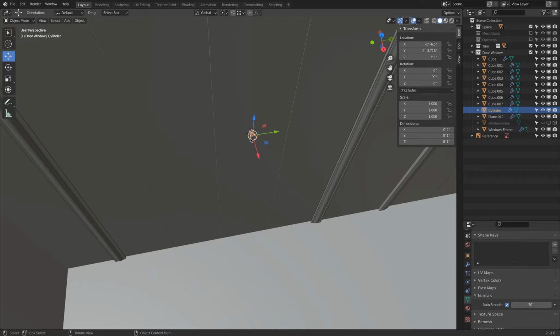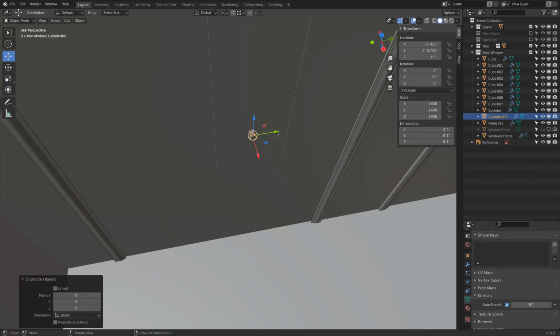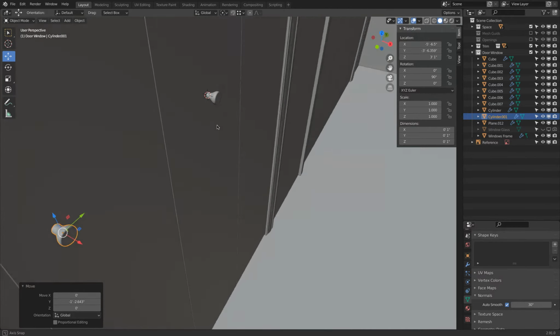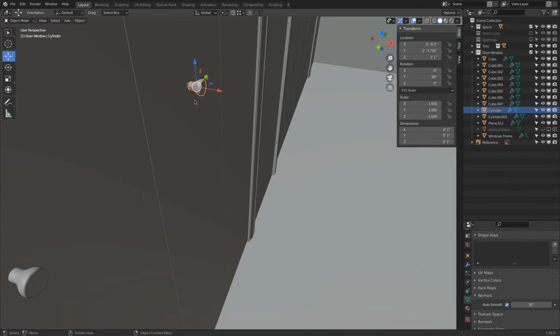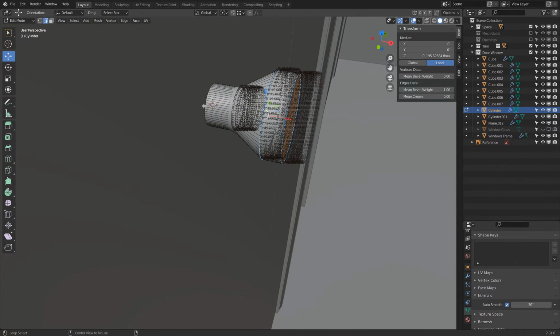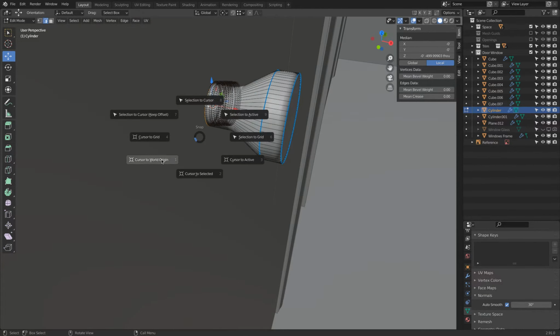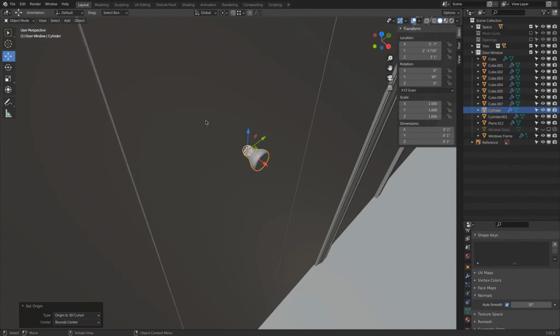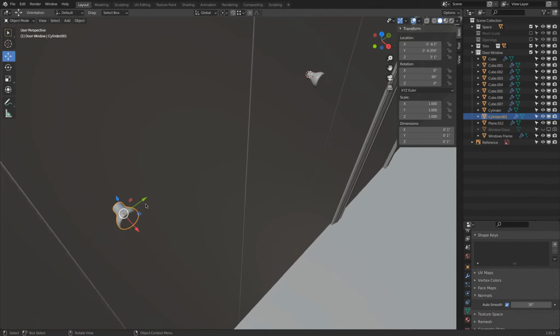And this time we will do this via the screw modifier. We will use this as a reference. So Shift D and escape. Move this to there. First, actually, let's go back to here. We go to edit mode. Alt click the base, Shift S, cursor to selected. In object mode, right click and say put it onto there. That's important actually for what we're going to do.